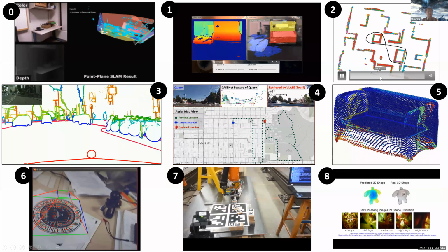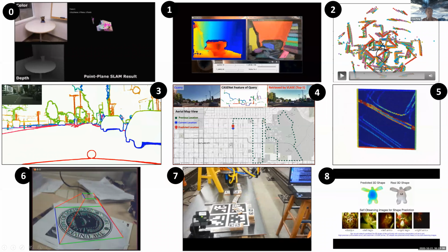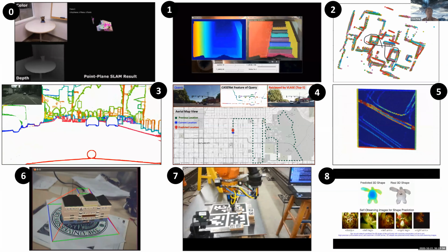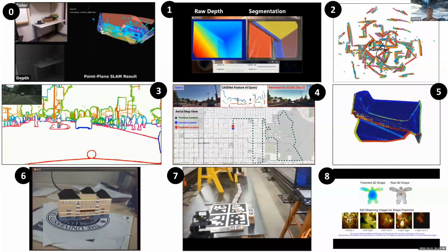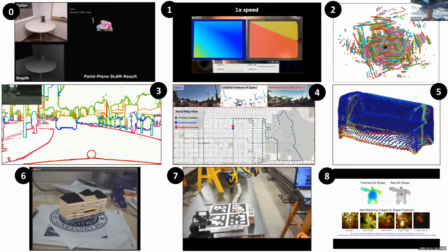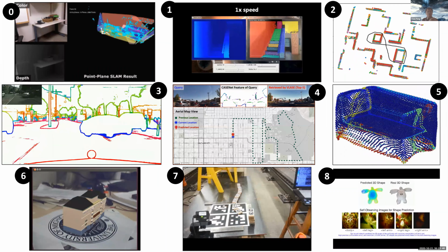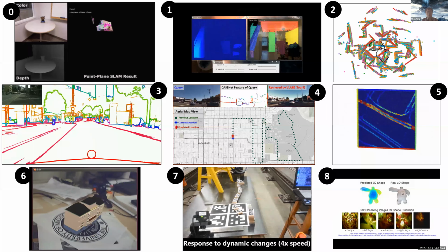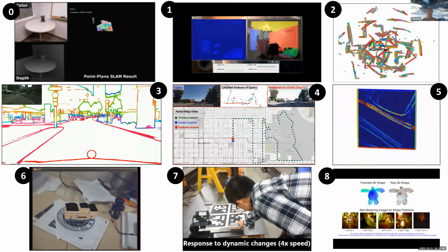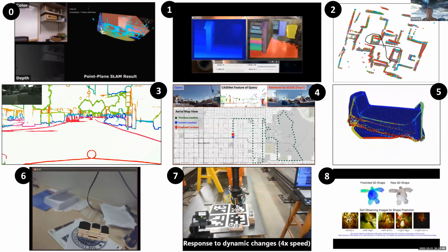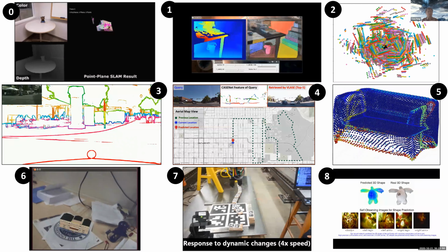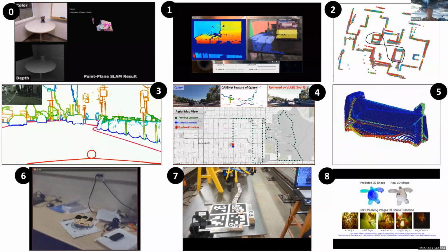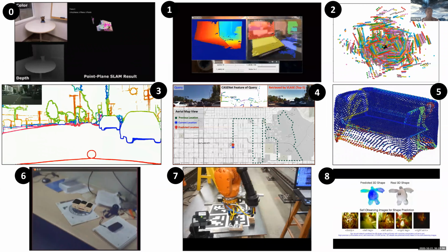What we did in number 2 is a method that utilized the state-of-the-art. Actually, we developed a state-of-the-art AI-based solution using a deep neural network to automatically align the point cloud. So we just input all the point clouds scanned by the LiDAR, and the network will automatically figure out the correct way to align them into a joint coordinate frame without any human intervention. That can save a lot of labor because you would otherwise need to install markers or have someone roughly align them.